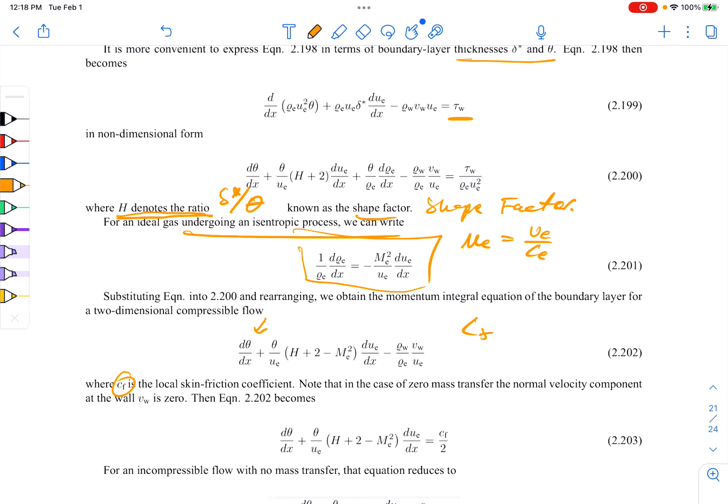And C_f is the skin friction. So those of you who've worked in some aerodynamics work, skin friction, of course, is a non-dimensional way to look at the stress on the body locally. So it's often something you would want to try and predict, like an airframer company like Boeing, Airbus, or Lockheed. What's the skin friction in your vehicles? You want to minimize that.